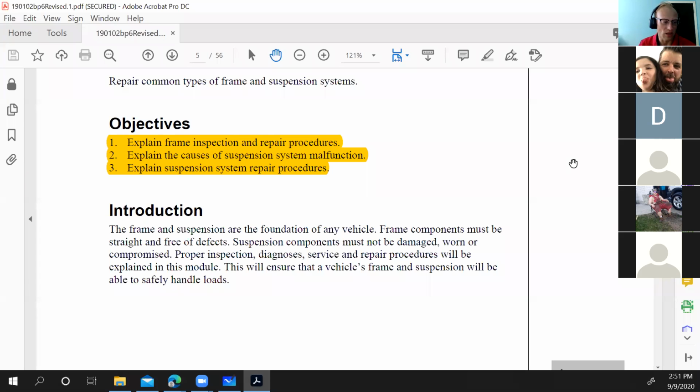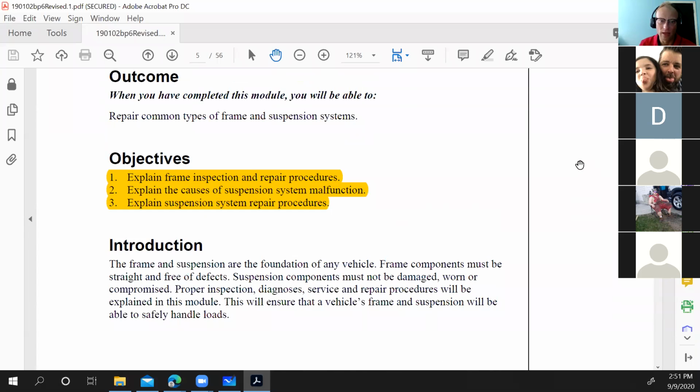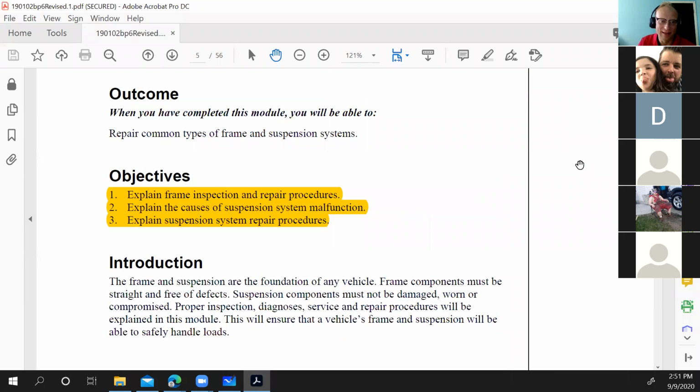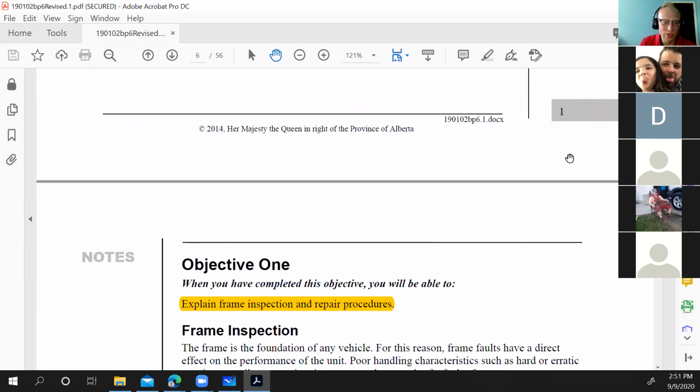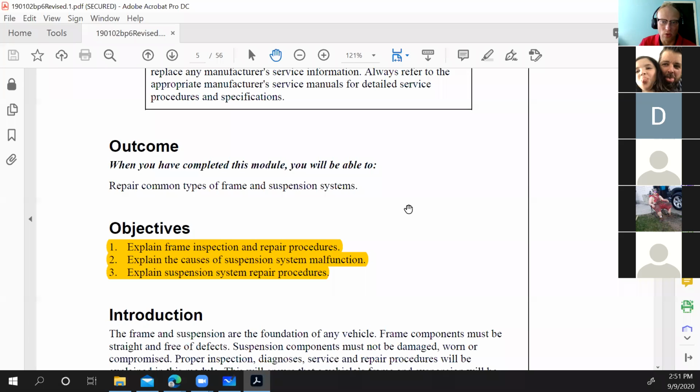We'll talk about repairs like that, what you can do, how you go about plating. I drilled a 3/8 hole in the flange on the top. Yes. Big no. Very bad. You wouldn't think it is, but even that small hole, even one bead of weld that goes across a portion of the flange can weaken it quite substantially. Yet again, there are circumstances where you might have to do that, but it's going to be controlled and under very specific circumstances when that happens. Okay?